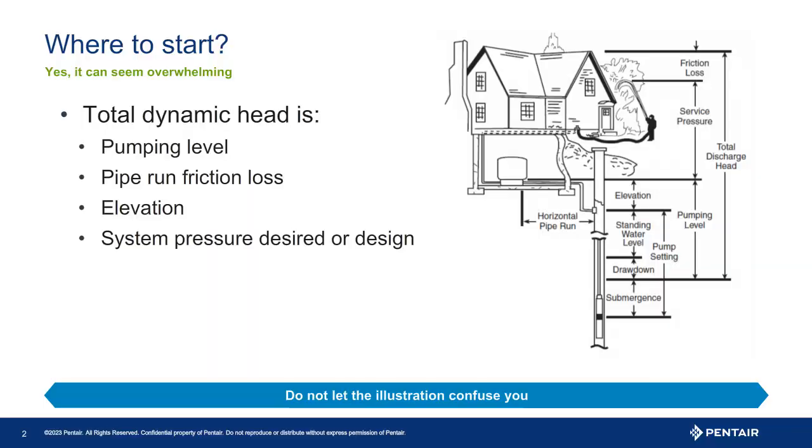So why is total dynamic head so important? Well, first, for sizing of course. Second, to use sizing programs that can show multiple conditions, which is handy for understanding how the VFD will run in the system. Last is to better troubleshoot the system.